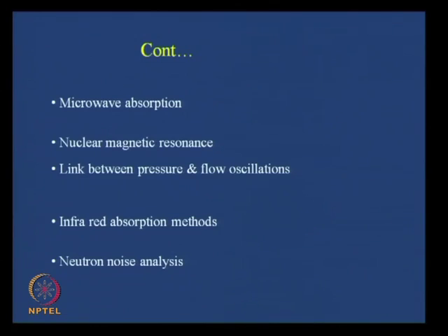Electrical impedance again works for low quality flows. The beauty of infrared absorption is that it works for high quality flows. So, if we have to go for high quality flows, it is very good for air water, steam water and such flows. This is one.